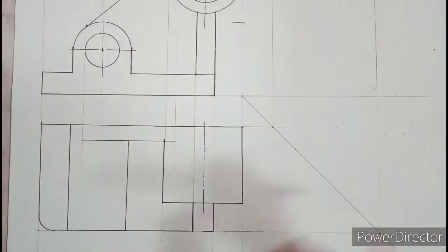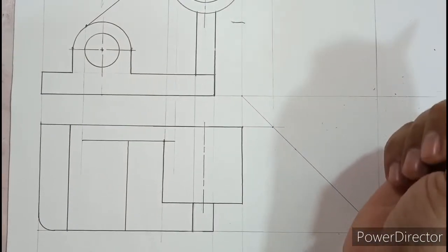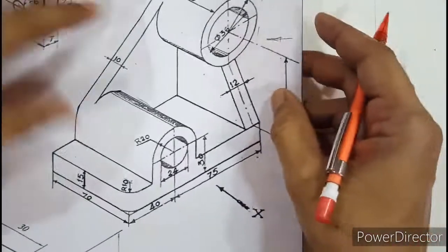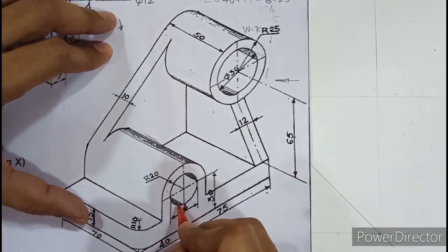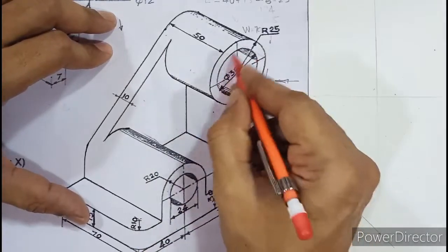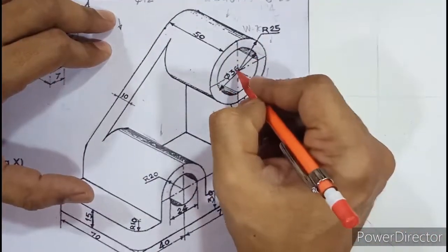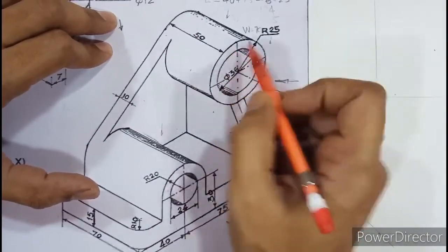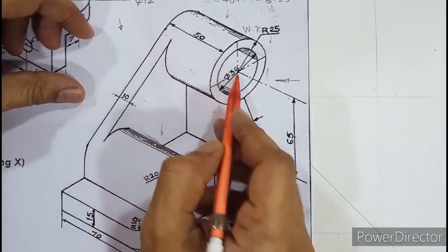Yeah, now once this is done, what is left now? Obviously our favorite hidden lines are left. So let us see some easiest hidden lines and then we'll see the difficult one. So the easiest hidden line what can be understood is, so at this point of time you should be able to understand that circular holes first and second are easy to understand because they cannot be seen from the top view. So this hole is of diameter 36 and it travels 50 millimeter inside. How much 50? Because the depth of the hole is not given. So if I put my pencil from here, it should come out from the other side. So the depth of the hole will be 50 itself, isn't it?